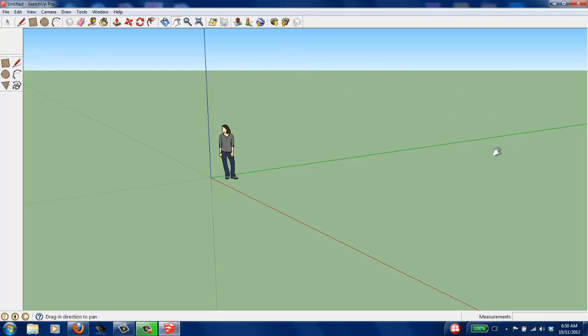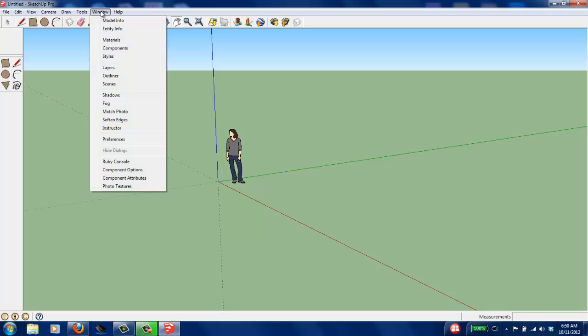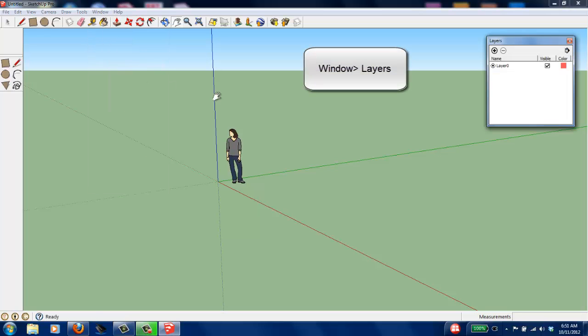So before we get started, I'm going to open up a couple of palettes in the Creative Suite parlance. And remember, in Creative Suite, if you didn't know where a tool was, you'd use the Window pull down and find it. It's not 100% true in SketchUp. The tools are in different places. The first one we're going to look for is our Layers window. That one is under the Window pull down. I'm going to Window, Layers, and that pulls up my Layers palette.